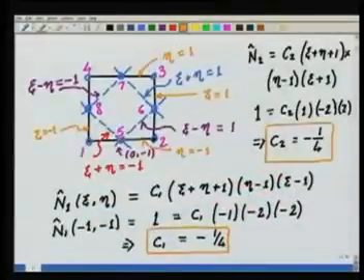What about a mid-edge one? A shape function, let's say function 5, 6, 7 or 8. I'm going to form the generic function N7, let's say. N7 should be such that on this edge, these shape functions should become the standard one-dimensional shape functions of order p.